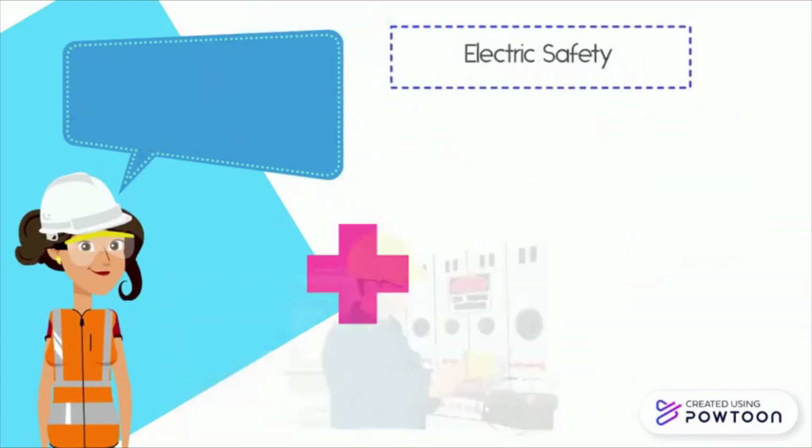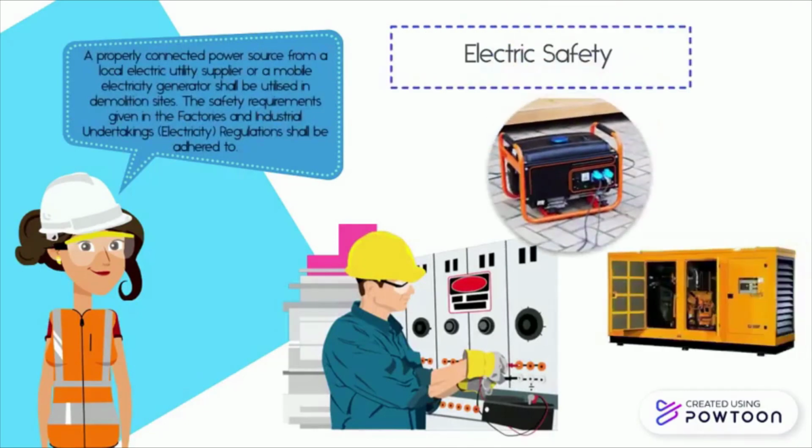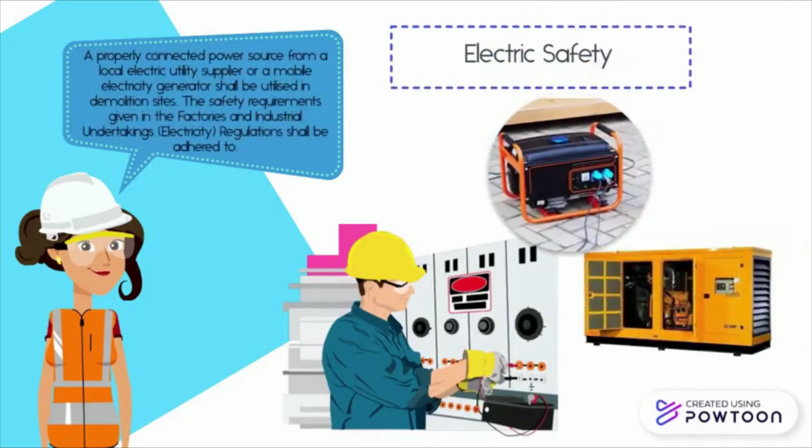Next safety and health is electric safety. A properly connected power source from a local electric utility supplier or a mobile electricity generator shall be utilized in demolition sites. The safety requirements given in the Factories and Industrial Undertakings (Electricity) Regulations shall be adhered to.